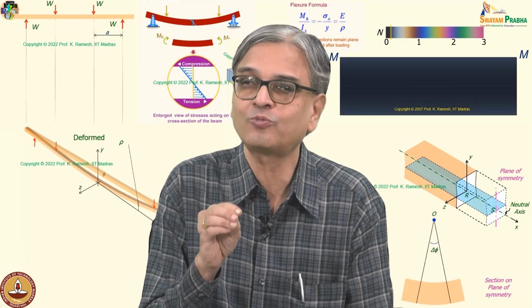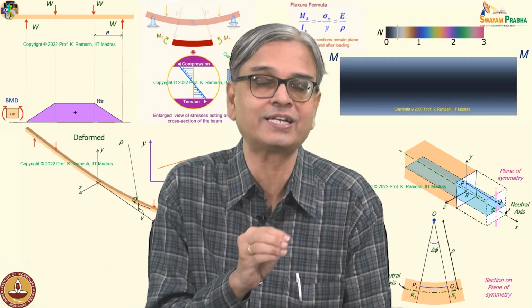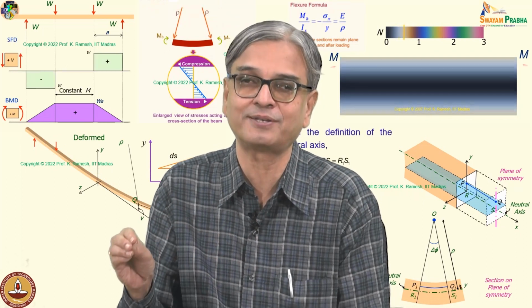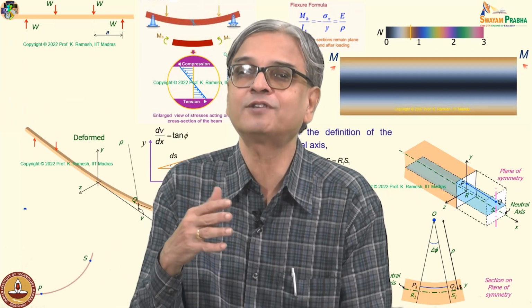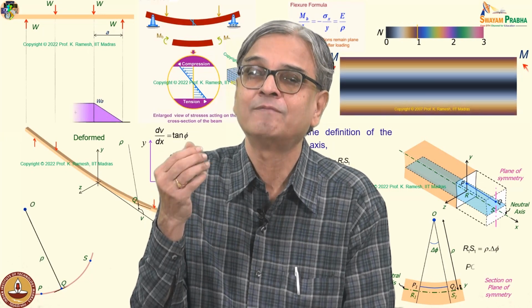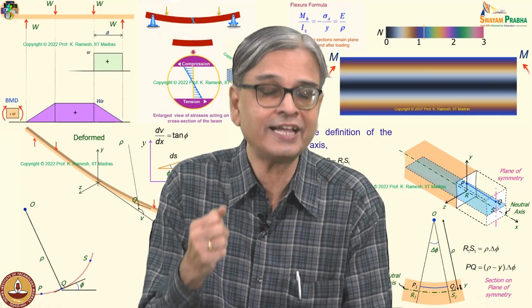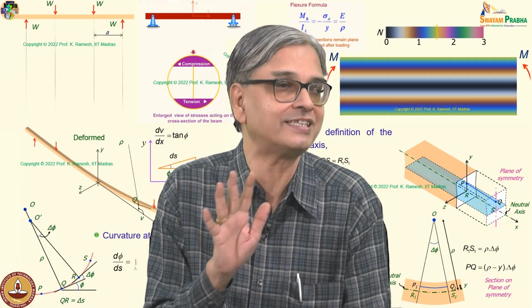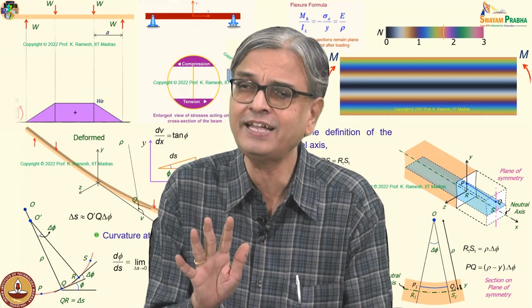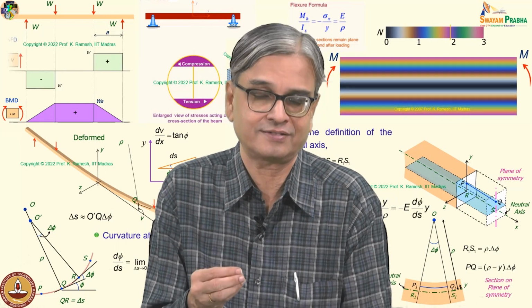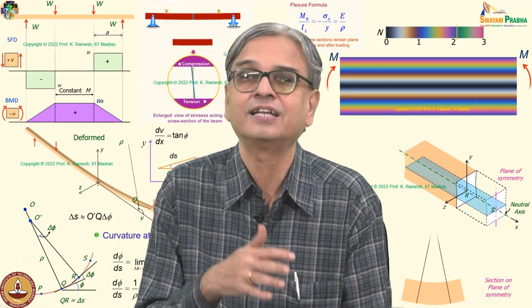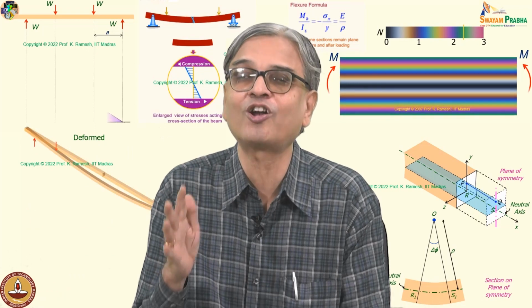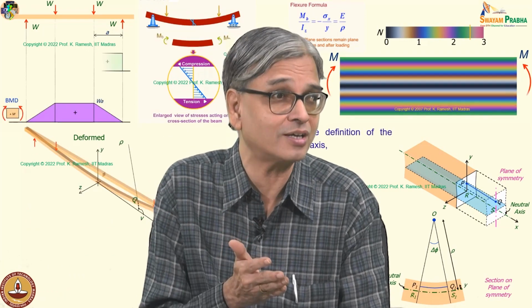See, people do not want to forget that they have graduated from rigid body mechanics to deformable solids. So, even the deformable solid, whether it has resistance towards bending, resistance towards torsion, they qualify it by the respective rigidities. If those rigidities are high, it will not twist when I have high torsional rigidity. If I have high bending rigidity, it will not bend that easily. That is what you want.